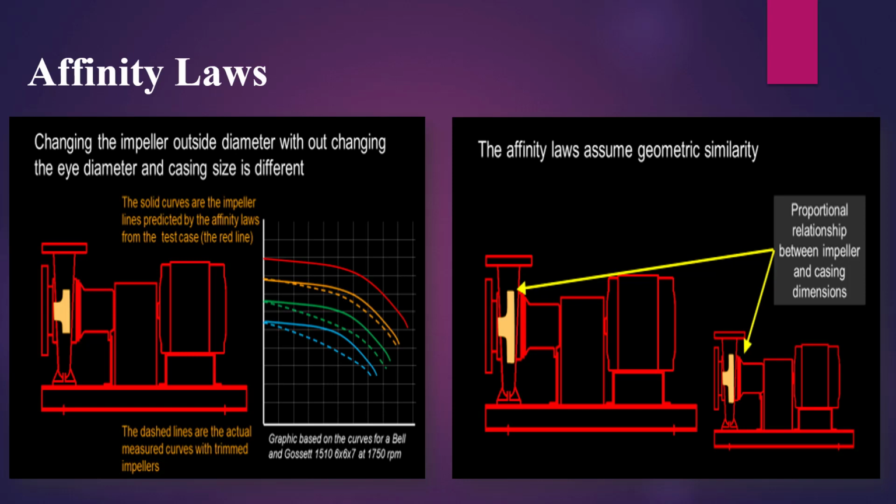So, if you have a fan or a pump that doesn't need to run at 100% flow or pressure output, you can reduce the shaft speed, and hence the power consumed by the fan. This is an example of an ideal curve of power compared to flow, based directly on the affinity law. Note that real devices will have curves that are offset or a different shape because real devices are not ideal and have varying performance characteristics. Even a small reduction in speed can result in a significant reduction in power consumption.